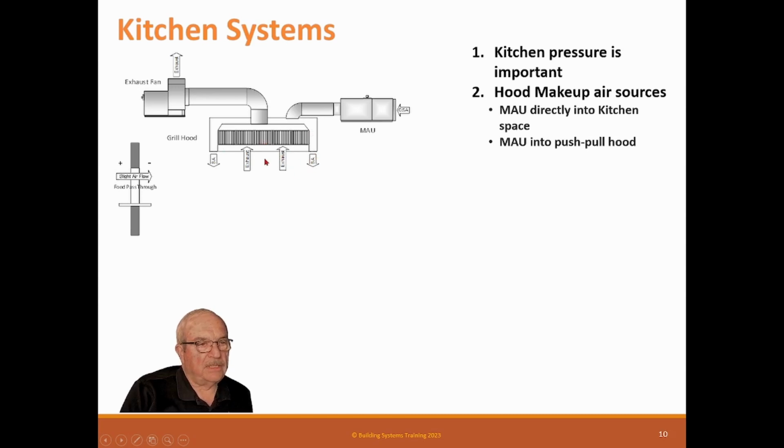So then it is kind of important how this works. Some chefs prefer ones that have a large area of perforated metal so that the air is very slow velocity and just kind of comes out into the space. It'll come out like this, be sucked back in. Some prefer that they have louvers here, regular grill louvers, so they can direct the air where they want. And there's always a decision: do you want the cooks to be in this stream or do you want the food to be in the stream? So that's important, what they decide, how they're going to push-pull it.